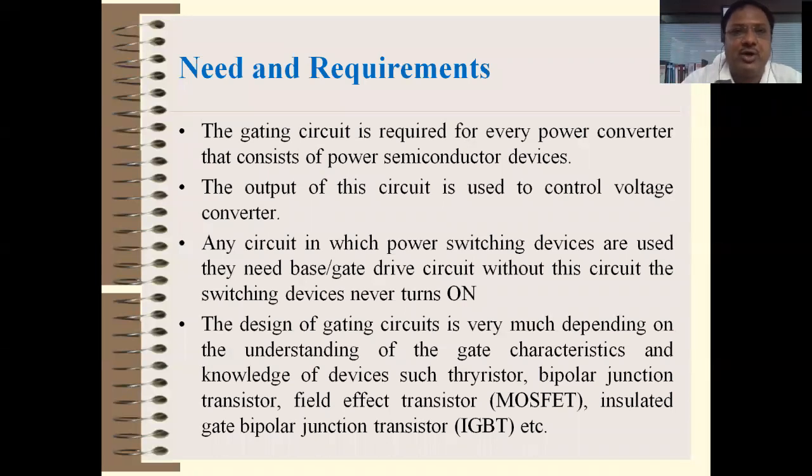One of the devices of a converter or inverter or a chopper fails, or maybe it burns out, or sometimes there is a breakdown. In that situation, if the power device breaks down, a large current may flow through the gate of these devices, and that current may damage your logic circuit or drive circuit. So drive circuits require isolation between the power circuit and this low voltage circuit, called the logic circuit.